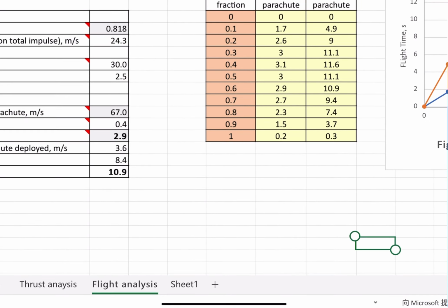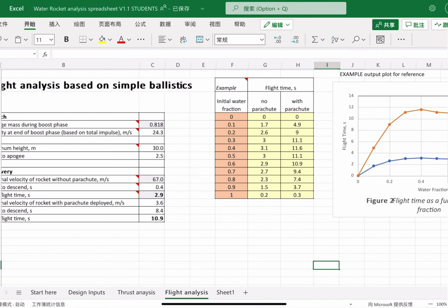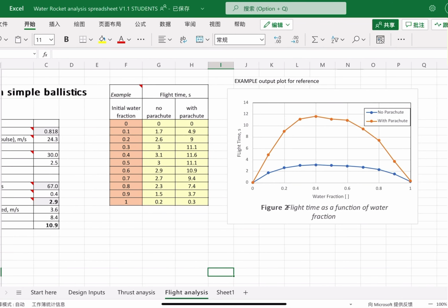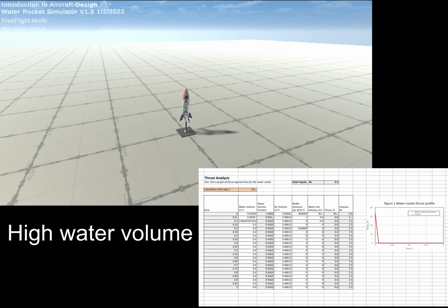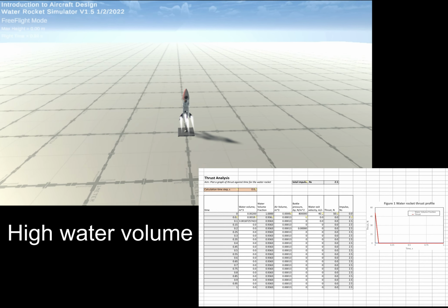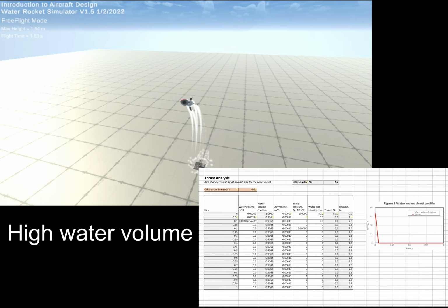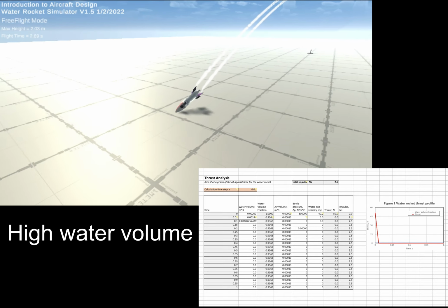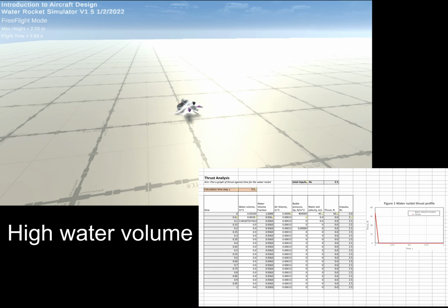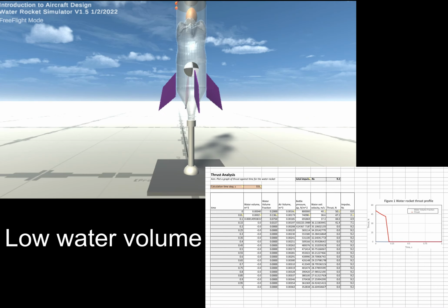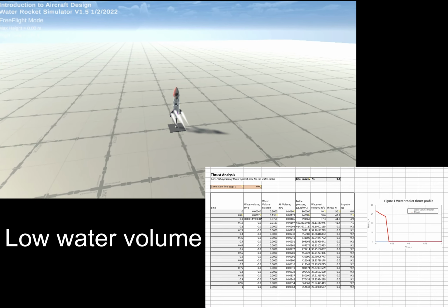With deceleration being one of the most critical for the egg's safety, it is important to strike a balance between deceleration and force. Finally, I'd like to talk about the integrated design. The size of the rocket or volume will have an effect on the launch of the rocket. We've considered a 2-litre bottle for this launch. The volume of the rocket will determine the maximum amount of energy which can be stored in the compressed gas, but also being aware of how much pressure we are dealing with.